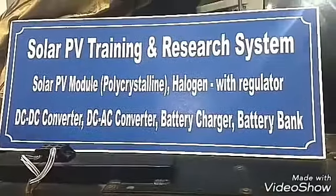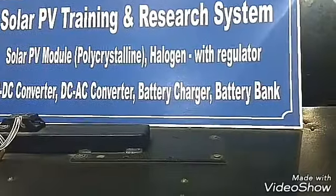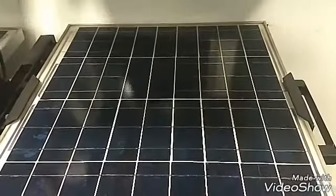We are demonstrating a project that is the design and implementation of a battery charging circuit using a solar panel with a power rating of about 40 watts in ideal conditions. The open circuit voltage is about 22.32 volts. The short circuit current is 2.42 amperes. The rated voltage and current are 18.1 volts and 2.21 amperes respectively.